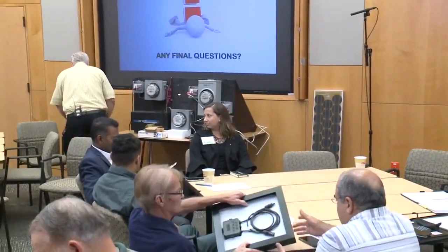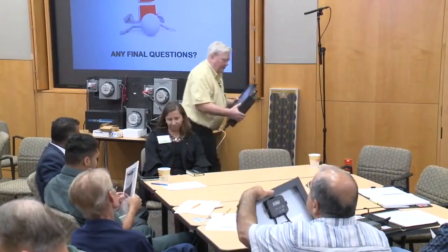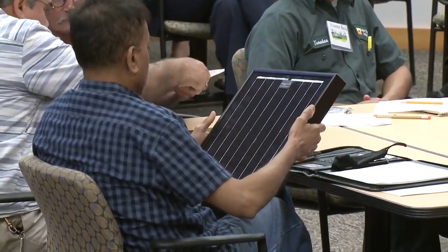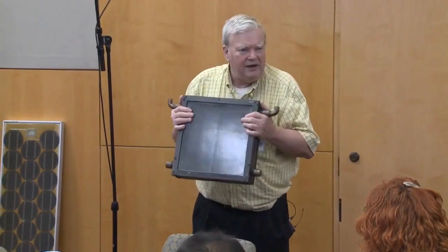Now, one of the things that we talked about was hot water. I'm just going to get a little tiny plug. This also is a little demonstrator. Cold water goes in, hot water comes out. We talked about efficiency. If you're hung up on efficiency, solar panels generally are around 20%. The rest of it comes off as heat, pretty much. Hot water collectors are between 80 and 90% efficient, meaning 80 to 90% of the sunlight energy into this thing is converted into hot water.